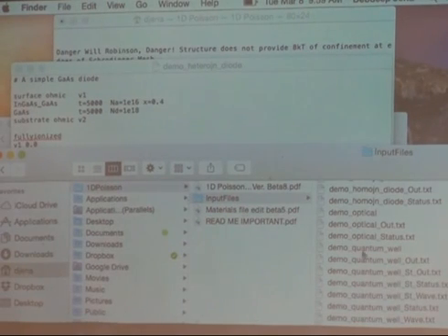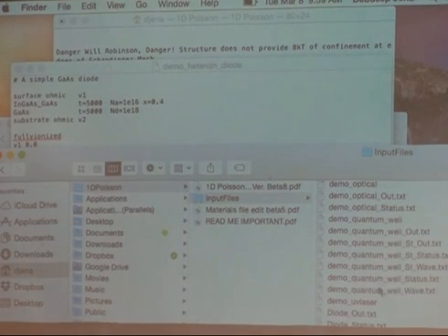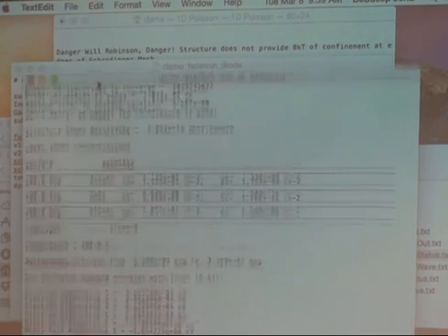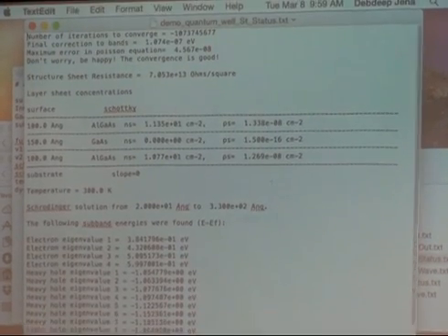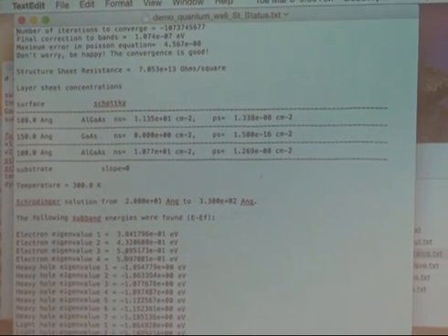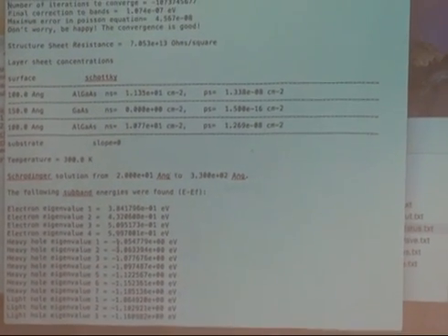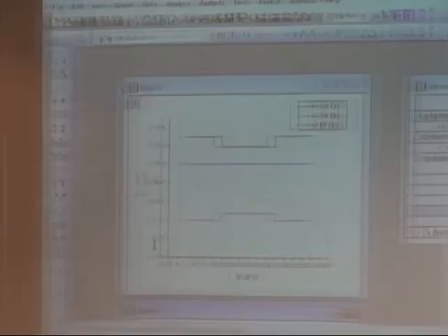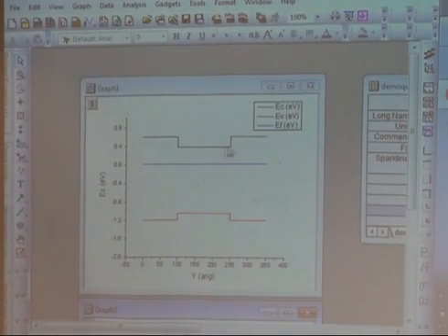And where is that information sitting? You go to status, let's say. So here are all the electron eigenvalues and hole eigenvalues in that quantum well. Four bound states, starting at 0.38 eV to 0.6 eV. So 0.38 eV is the lowest state. Then you have 2, 3, and 4. 0.6 eV is just very shallow, and then it goes out. It's not bound anymore. Similarly, there are a few finite hole states.